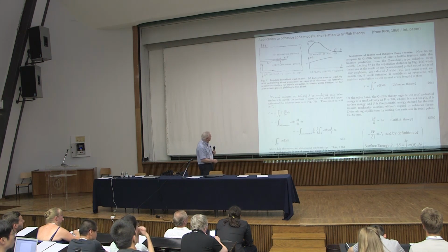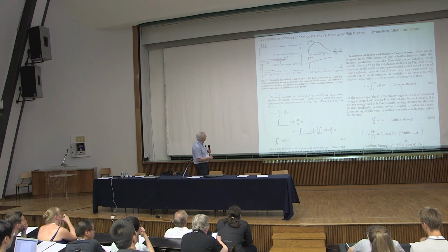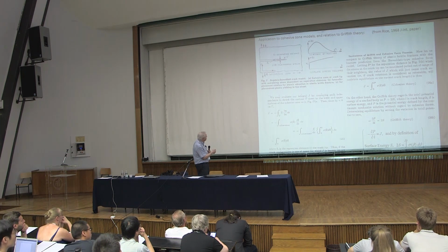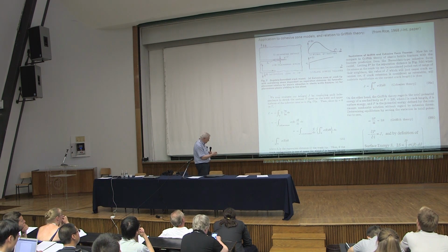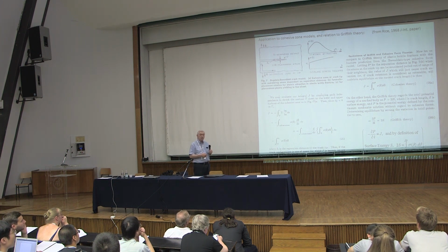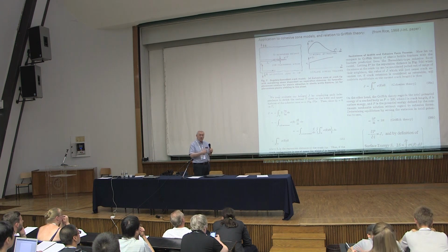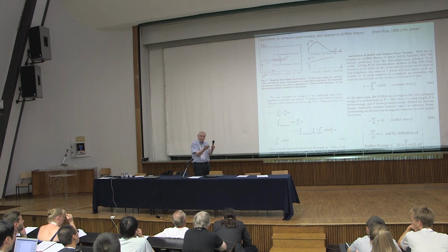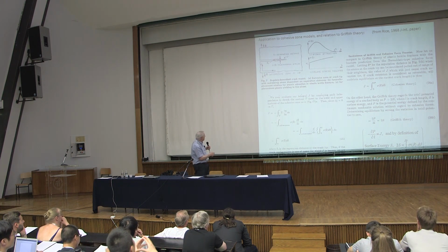Okay, I think that's that. Now, here's an application of this path-independent integral idea to processes of gradual decohesion. And these have been used in the literature on fracture in two different contexts, at least that I can think of. One was by Dugdale in Britain as a simple model for yielding of thin sheets in plane stress. He observed in the lab that when you had a crack in a sheet and you loaded it, you would often find that the plastic zone of necking developed in front of the crack. The material would suck in, and you would then have plasticity confined to a narrow line ahead of the crack.